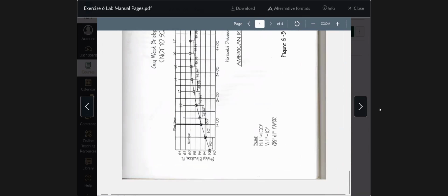Vertical scale, make sure you put the first row, the first labeling vertically, it's got to be less than... you probably want to start at 40 there, because your most likely manhole is going to be around 45.466, and the bridge is going to be a little higher than that. So make sure that the number that you start labeling your vertical scale at is not lower than 45. Okay, so when you get up to 50, you'll be a little bit above the bottom of the drawing.